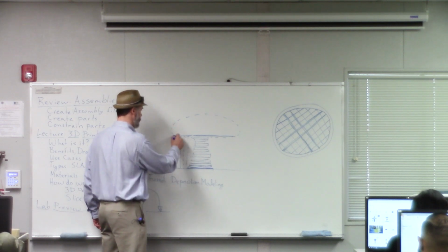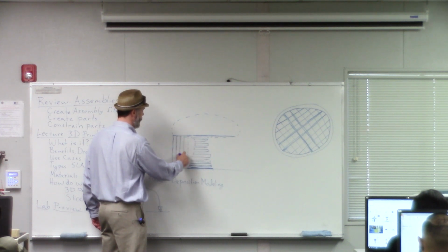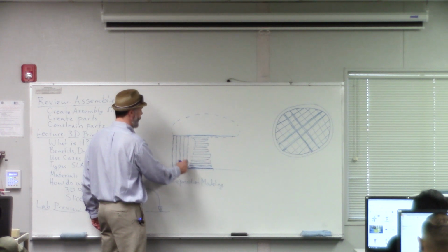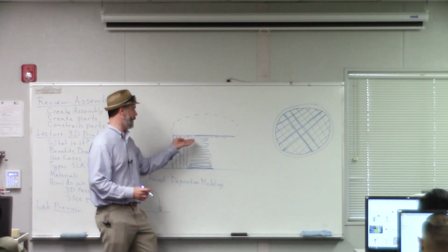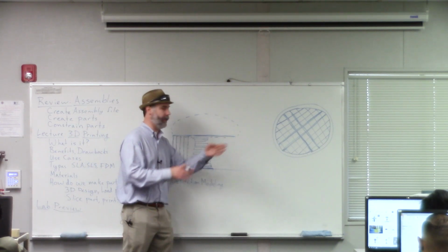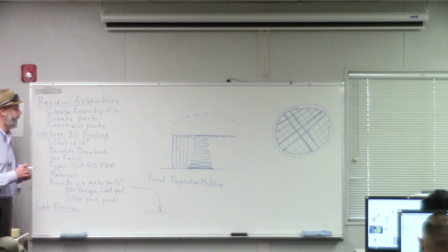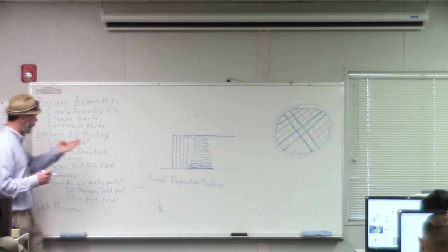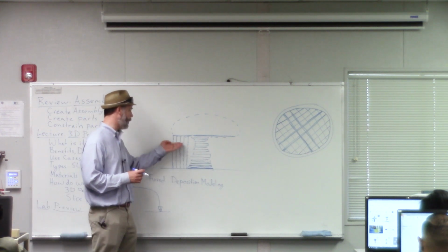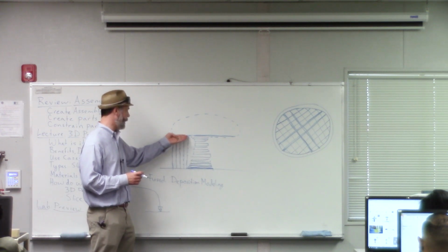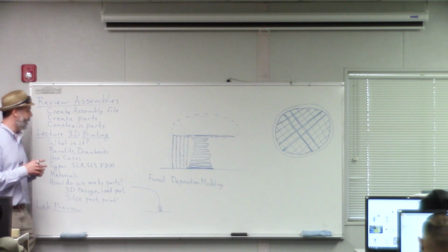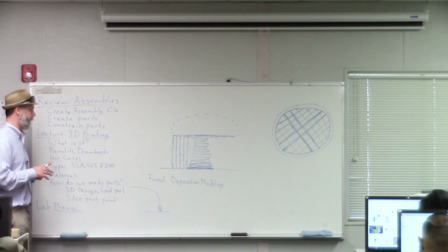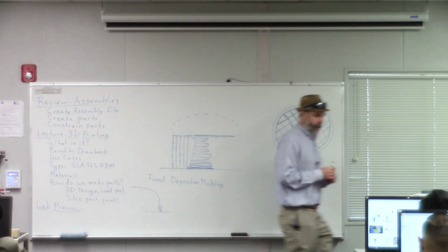So if you tell the 3D printer that you want supports, the slicer will go in and add these extra little pillars to hold up the parts of your shape that extrude out and that would otherwise fall down. Okay? And then typically these supports are fairly small and relatively weakly attached so that it's easy to break them off after you're done. And yeah, they can just fall away.